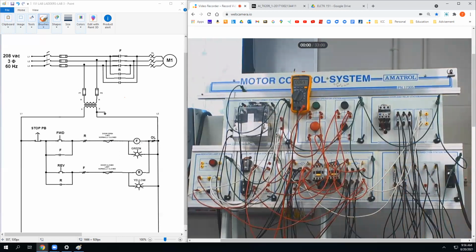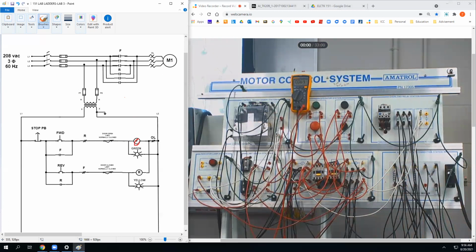So neither of these are pulling in, right? The motor's not turning on, but that's not the output we're looking at because neither coil is turning on. So if it's me, I'm just picking one. You're right. So, well, okay, let's go down that road. Neither of these are turning on, correct? So if a problem is here, it's most likely up here too. If that's the case, these are identical until you get to somewhere in here. More specifically, here. Okay, Heath's right. Let's start at the stop button.